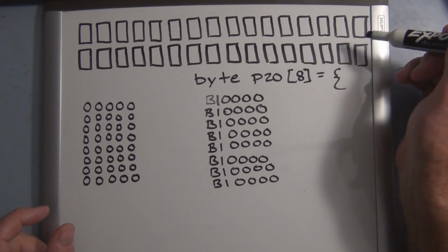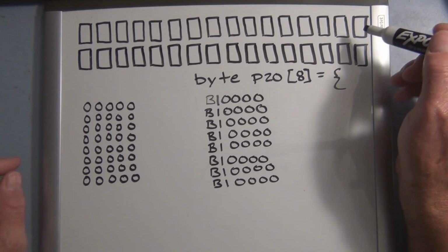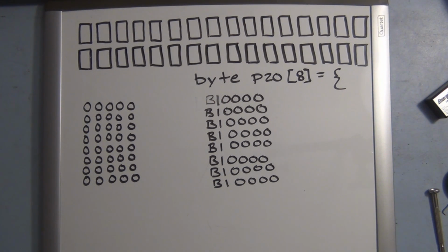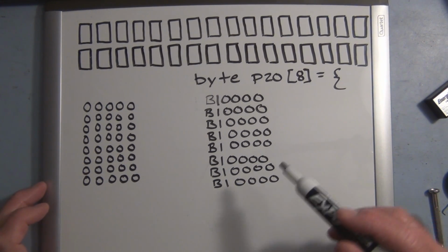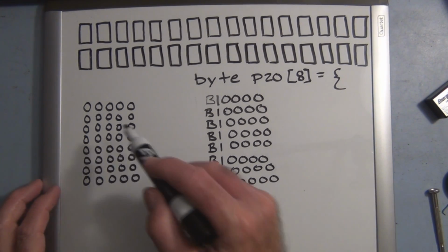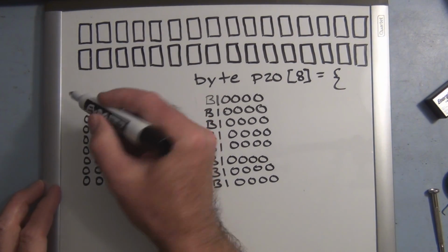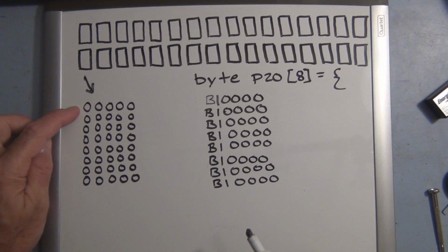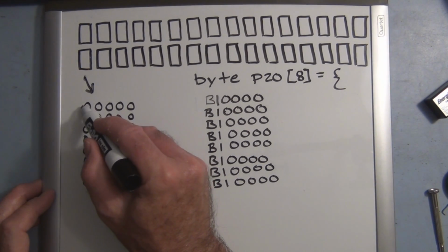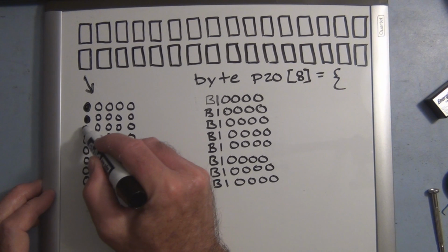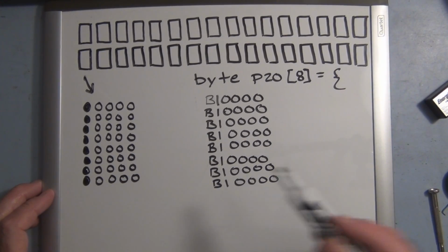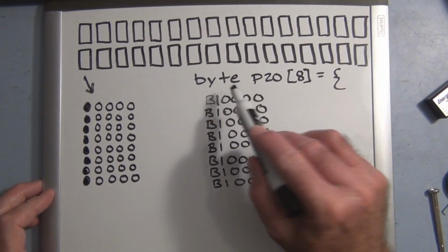So here we have the squares associated with a 2 by 16 LCD display. And the way we create those special characters for the bar graph is, for instance, if we look at one of these squares, these are all the dots associated with one of those squares, which is 5 by 8. We have to turn these on. That's the first special character. And we do that with this byte.